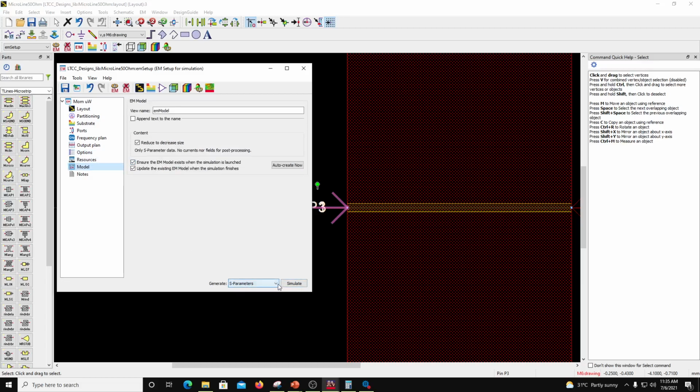And here there are different options, but I am going to compute S parameters. So it is automatically going to mesh first, then compute green functions, right? Green functions are for the substrate, and then mesh. Now, what are green functions?